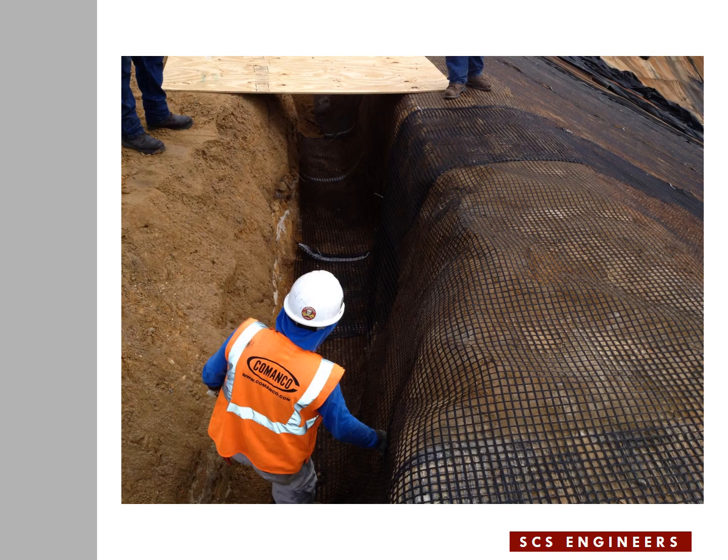Here is the anchor trench for the geogrid. When you use geogrid in the lining system, the anchor trench plays a significant role in keeping the system in place, because the interface friction angle between the geogrid and the geomembrane that goes on top of it is not significant, meaning it has a low interface friction angle. So the only thing that will really play a substantial role in holding the geosynthetics on the slope is the anchor trench. That's why the anchor trench is so deep, in order to make sure that it has sufficient holding capacity for the geosynthetics going into it.